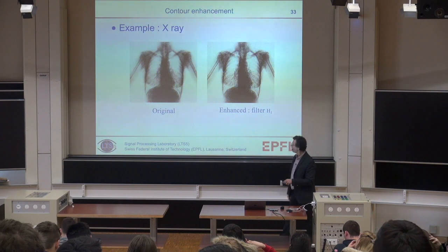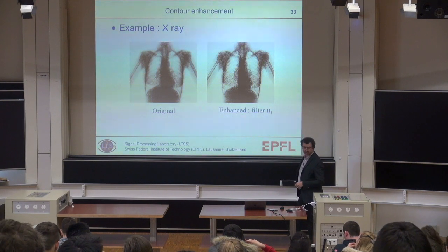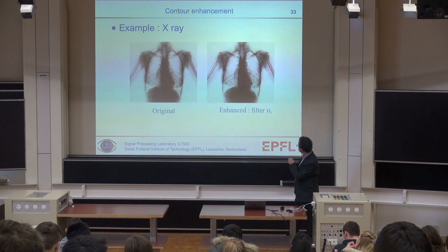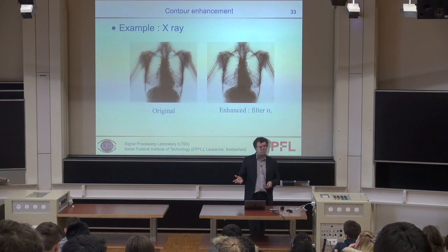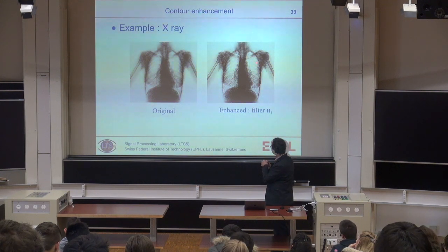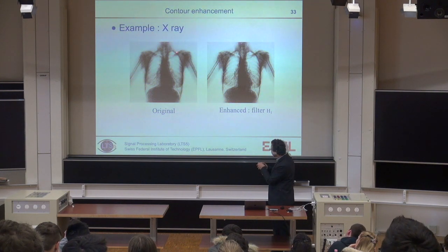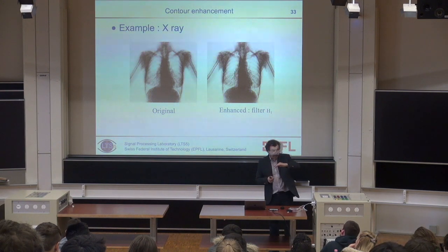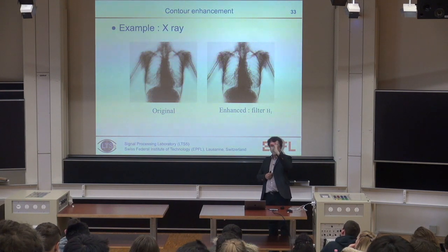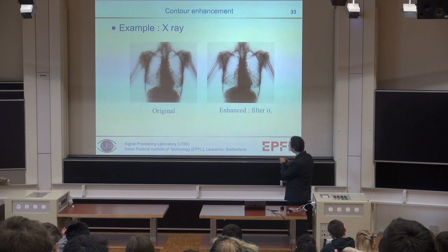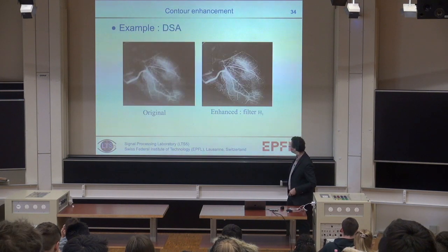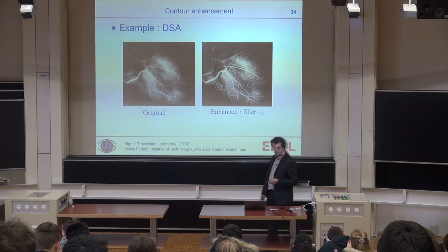On those very blurred radiographs, old archives of radiographs, we managed to get sharper edges. You see, you recognize. They're very bad images on purpose. By boosting a little bit the high frequency, you see them better. They are there. The contour here has some part of high frequencies. You just boost them by applying a high-pass filter. And it gets sharper. But also you get a bit more noise. That's life. You can sharpen your images. This is sharpening.